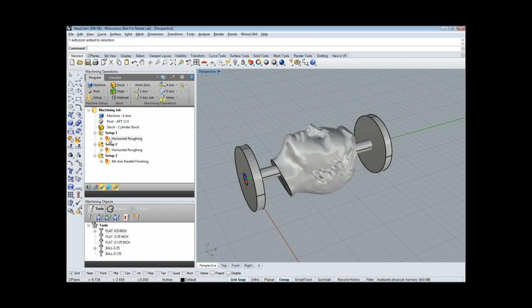And now I would like to generate my roughing toolpath, so we're going to program an indexed operation in here for the roughing process. So we would like to rough it from the top, rotate the table by 180 degrees, and generate a roughing toolpath for the bottom half of the part. And then we'll rotate it back to 0 and generate a continuous 4-axis finishing toolpath. So you can do a combination of indexed and a continuous 4-axis toolpath.